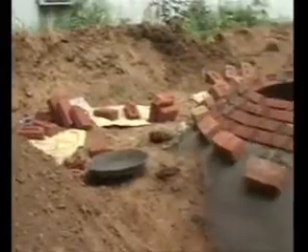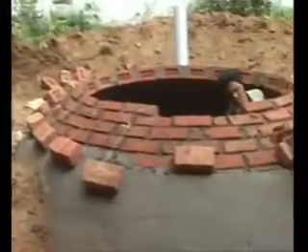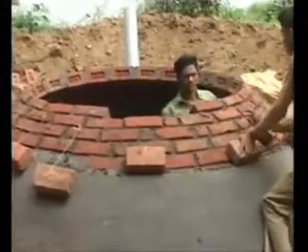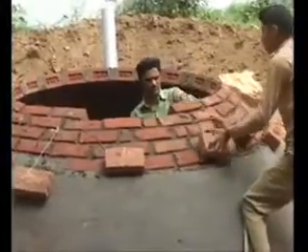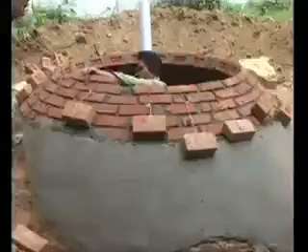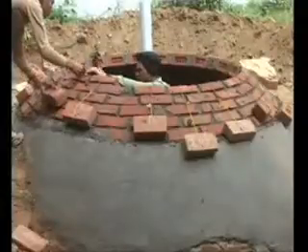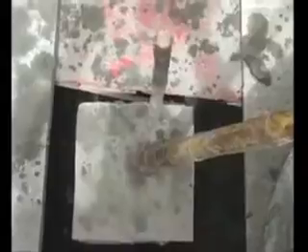Above 15 layers, another 10 layers are laid by using a 1:4 ratio of mortar mix. Counterweights are also applied for the stabilization of the wall. Next to it, the sizes of the bricks are kept 3/4 at the top. For the closing of the dome, shuttering is done from inside and then the gas outlet pipe is fixed.